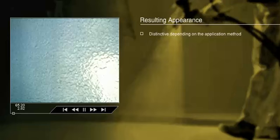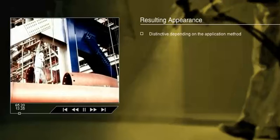It should be noted that there may be a significant difference in appearance of coatings, which depends on the application method. Brush, roller or spray application techniques all bring their own characteristic appearance to the finished coating film. Special paint rollers are often used to achieve specific finish appearance. Some coating types, including those pigmented with flake materials, for example aluminium flake, MIO, may be specially sensitive to appearance change, which reflects the application method and technique.